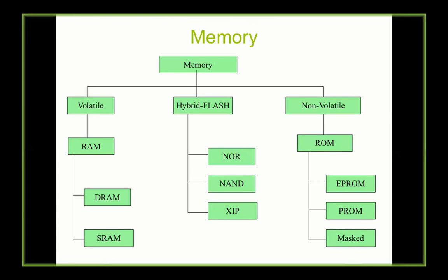So if the CPU has to talk to a flip-flop, it will be much faster rather than talking to a hard drive, which is magnetic. Or a CPU is much faster in talking to a flip-flop rather than using a NAND, which is based on MOSFET. So MOSFET is slower and flip-flop is faster. So naturally your response time for an application running on a memory is going to be a very high profile one. And if the application has to execute from flash, it is going to be hit by latencies, correct?